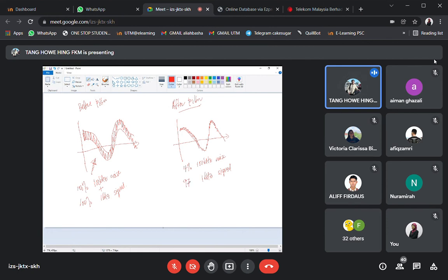All right, so 97% of the 1 kilohertz signal is allowed to go through. So summing these two, we actually get this. Okay, so this signal is made up of 4% amplitude of 100 kilohertz noise, plus 97% of the 1 kilohertz signal. Okay. Now are you clear about it? Have I answered the question about that fluctuation?